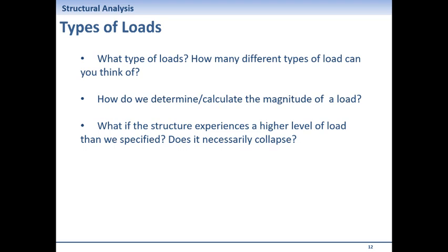One thing that you need to be quite vigilant about is that these standards get revised every few years. And you need to make sure that if you're calculating the live load today, this morning, you're using the most recent version of that standard. If you do not check it quite regularly, there's a chance that you may be using the older version.